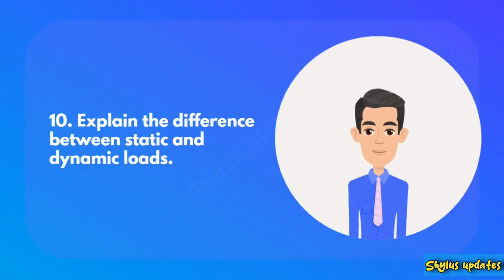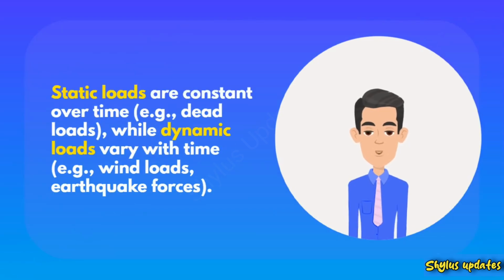10. Explain the difference between static and dynamic loads. Static loads are constant over time, for example, dead loads, while dynamic loads vary with time, for example, wind loads and earthquake forces.